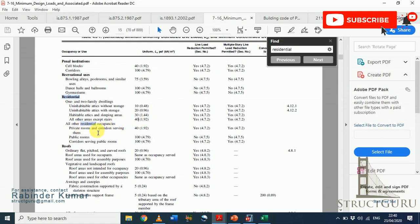All other residential occupancies, private rooms and corridors serving them, again we have to choose 40 for these categories. For public rooms we have to choose 100 PSF. For roofs we have to choose 20 PSF, because we don't have a lot of movement of people and objects there, so that's why the load value is reduced to half compared to the loads at other floor levels.